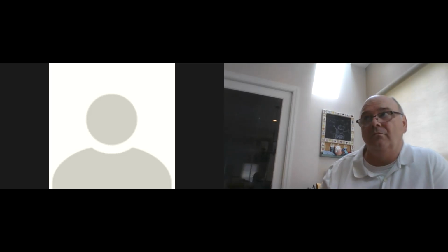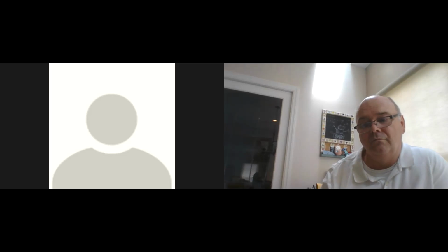I just did that on my IMU because it puts out like 3 pages of debug messages as the thing starts up. But if I feed that to my ROS driver, it's going to say, oh, those aren't valid numbers. So I just put a thing at the top. I said, pound define debug. Then down in the code, for every print statement, I said, if defined debug, then do this print statement, and then said, pound endif. And that way I can just go change the line that says pound define debug.